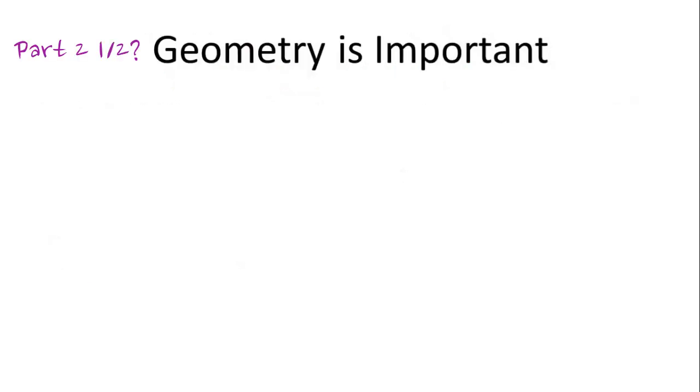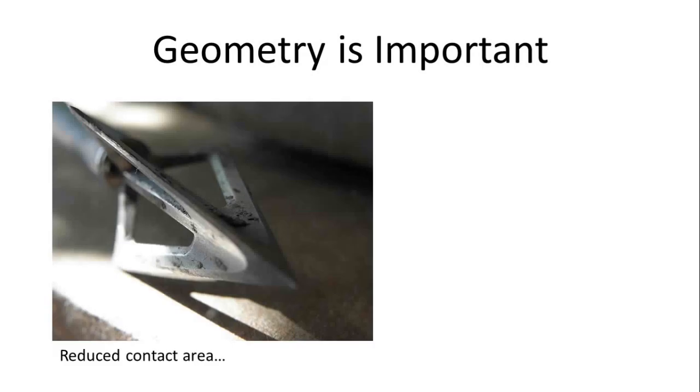Geometry of the colliding objects is a very important consideration because it determines the overall stiffness of both elements and it affects how the collision force is applied or distributed. Remember, the material properties are measured from stress curves, that is, force per area. Sharpen the projectile to a point, and the reduced area of contact increases the stress and the chance of material failure, resulting in the projectile piercing the surface.